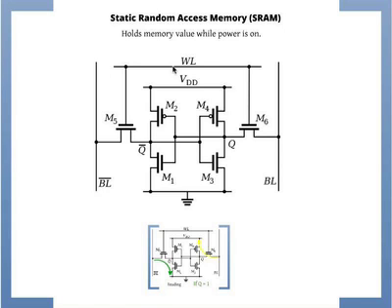So you have a word line coming in. This is one unit of that architecture, so we're looking at one of these. And you have a bit line here. You have a complementary bit line. The line on top means it's inverted. This is ground. This is VDD. Now you have 6 transistors here. M1, M3, M5, M6 are NMOS, and M4 and M2 are PMOS.